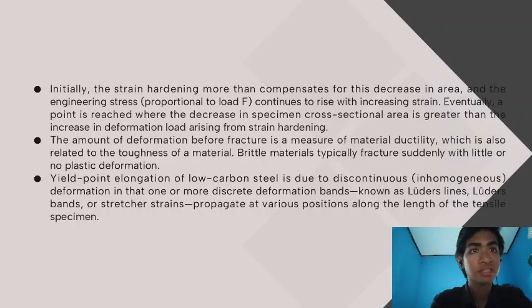Nominal tensile stress versus strain is sometimes called an engineering stress-strain curve, to distinguish it from a true stress-strain curve. The high point on an engineering stress-strain curve is defined in test standards as the ultimate tensile strength of the specimen, or simply the tensile strength. The point of fracture is called the fracture strength or breaking strength.